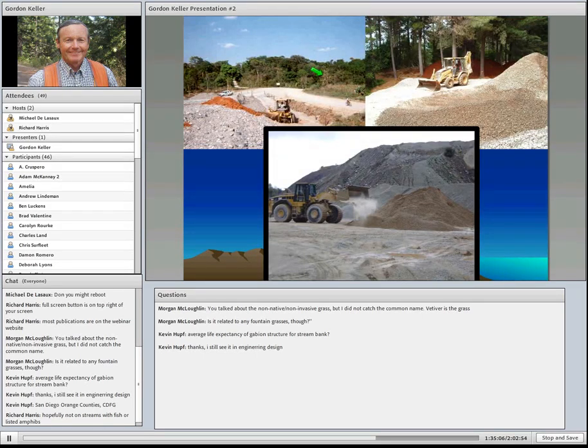Blending. This is something I've seen done in a number of different countries, including the United States here, where you're taking, say, a gravel, and it's similar to the last photo actually, but a little different. Rather than on grade, you're doing it in a stockpile area where you're mixing in some clay, something like here, into some gravel, physically mixing it with equipment, and then producing a mix that is better than either the clay or the loose gravel. So it's a poor man's way of producing a suitable material. It's improving the characteristics of either material.